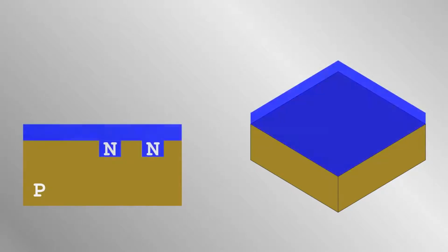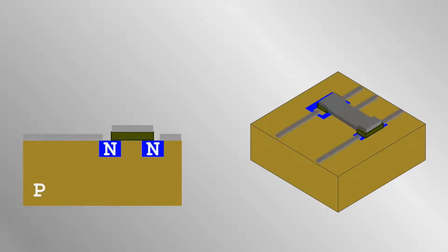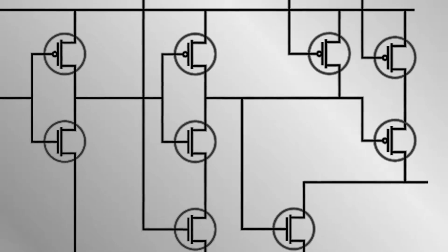The two techniques of deposition and etching used in conjunction mean that the N-type dopants for all the transistors on the die can be added simultaneously. Next, the silicon oxide is deposited and etched, and finally metal is deposited and etched away to leave metal channels on top of the die. These metal features form not just the conducting terminals of the transistors, but also the tracks equivalent to wires in a circuit, which connect the transistors as required. Every time photoresist is deposited, exposed through a mask, gaps are made and a die is etched. Finally, the billions of transistors are assembled and connected together by this method.